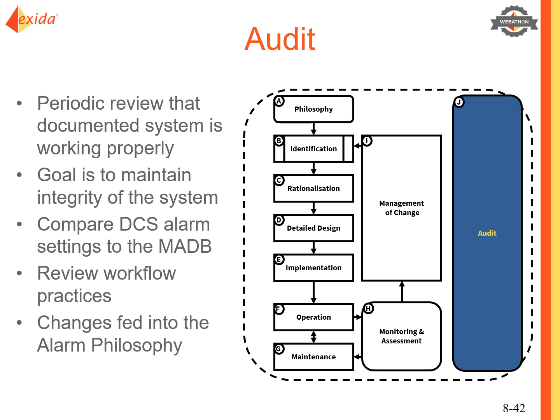Now, the last phase in the alarm management life cycle is an audit, and it's often carried out separately from the other phases of rationalization. There are two aspects or purposes to this audit. One is to compare the performance of the system to see if improvements can be made, and the other is to check that the alarm configuration is consistent within the system.